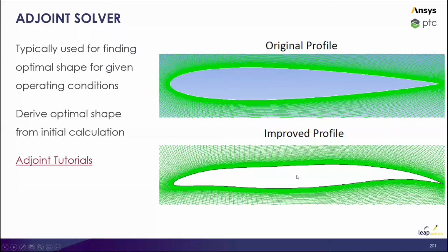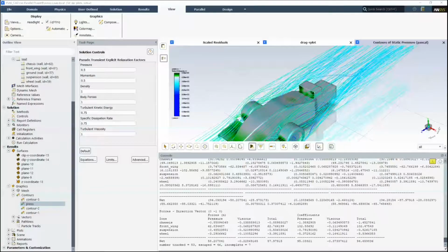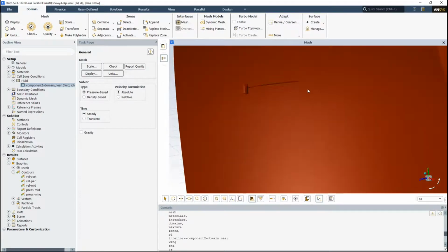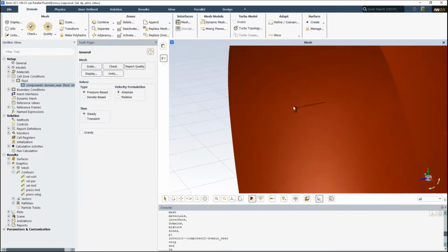So we did a representative propeller for a support case, just to get them started on using the adjoint solver, and the purpose behind it was to get a better thrust over torque. So it's like lift over drag for propellers, and a better thrust over torque would mean a better noise performance, because obviously we know with quad rotors, some of the biggest issues that we're having with them are they are too noisy, and the noise is unbearable. It's quite high pitched and annoying.